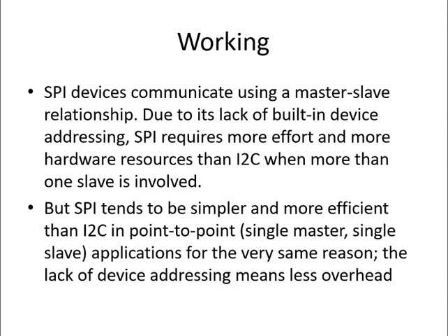Now, SPI devices communicate using master and slave. So here also you can see that master-slave configuration is available. One device will act as master and another device will act as a slave. But it is not using addressing, which means no addressing is available there. So SPI requires more effort and more hardware resources than I2C when more than one slave is involved. So normally you can go for SPI when there are less number of devices present there.